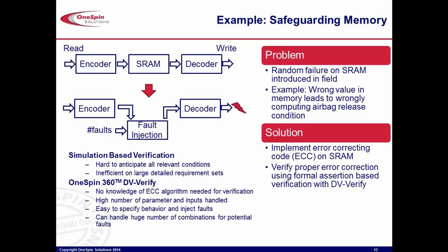You don't need knowledge of the ACC algorithm. It's very easy to inject faults and actually verify a huge number of combinations for potential faults, and ultimately do an exhaustive verification here that is totally impossible to do by simulation. And this is, for instance, also a case where formal can quite cleanly replace simulation.